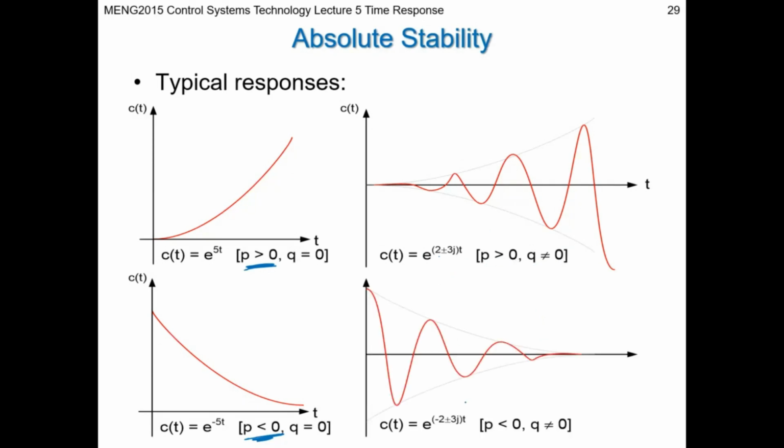And then the fourth condition is that you're going to have a negative real part and of course a non-zero imaginary part. So you've got a cyclical output. This transient term creates a cyclical output, but the window of amplitude is decaying, and it's settling that cyclical response down towards zero as time proceeds.